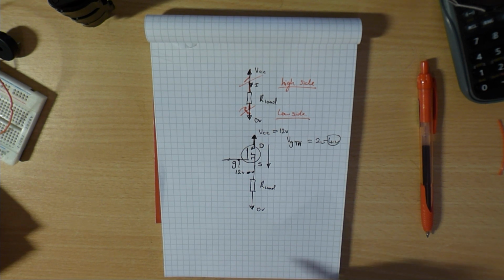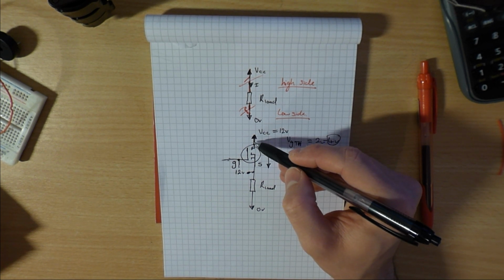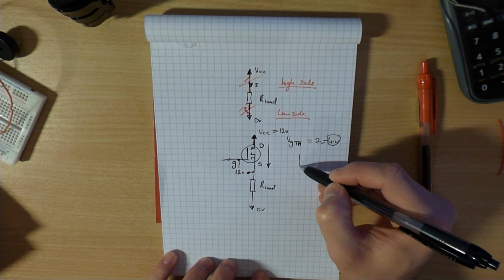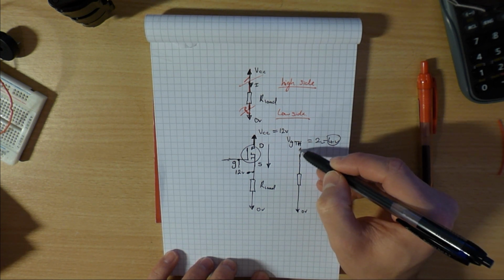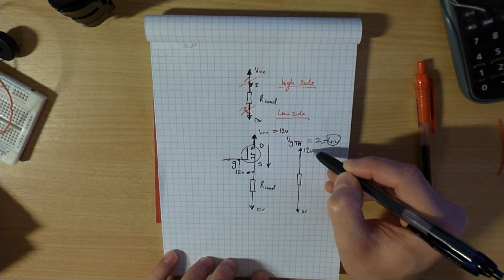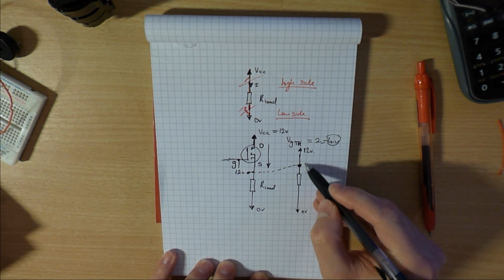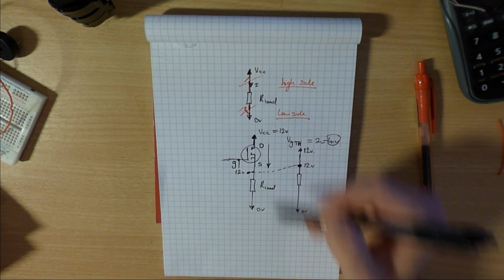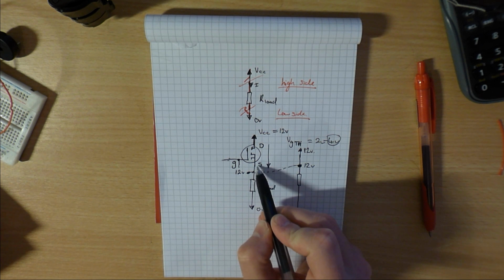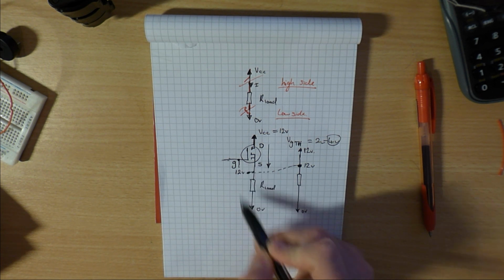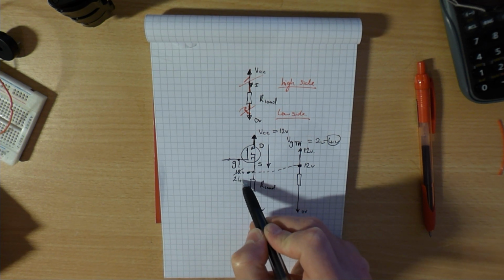And if my VCC is at 12 volts, I need to be able to put the gate 12 volts above this point. Okay? So let's take a little look at this circuit again and assume that the switch is closed and we get this. So there's 0 volts. Up here is our 12 volts. And right here is also now 12 volts, assuming 0 voltage drop across this switch here. That means that in order for me to be 12 volts higher than the source of this MOSFET, I need to provide not 12 volts but 24 volts.